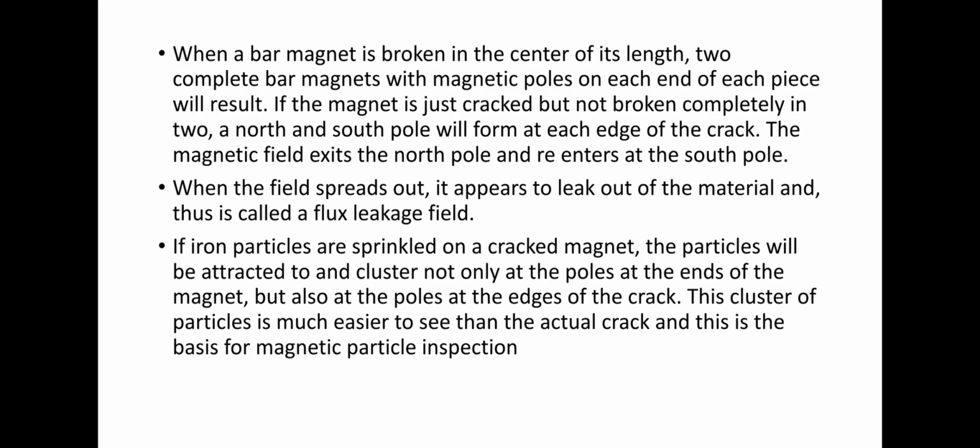If iron particles are sprinkled on a cracked magnet, the particles will be attracted and cluster not only at the poles at the end of the magnet but also at the poles at the edges of the crack. This cluster of particles is much easier to see than the actual crack, and this is the basis for magnetic particle inspection.